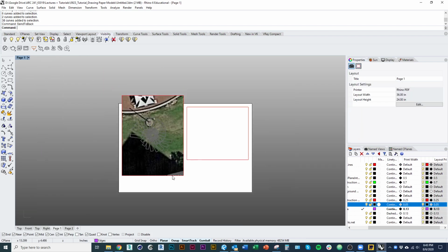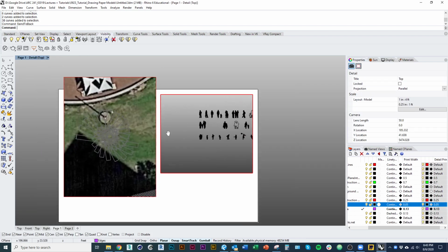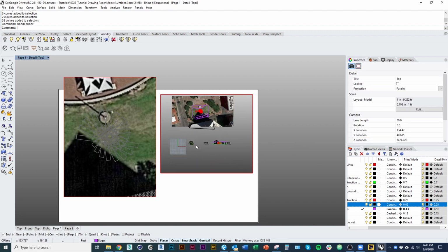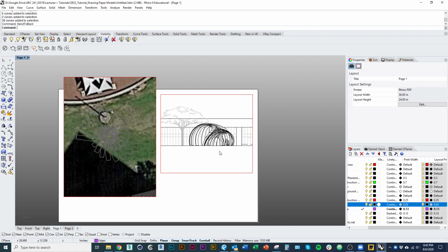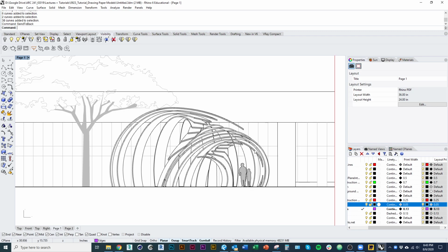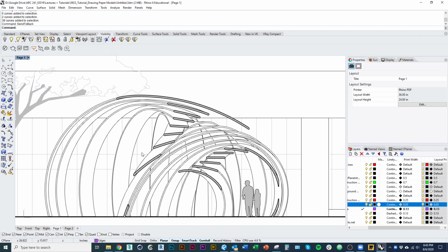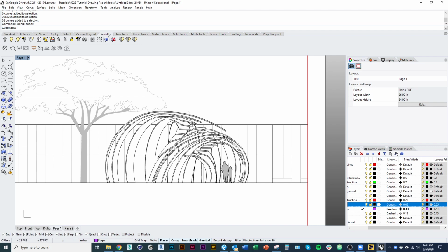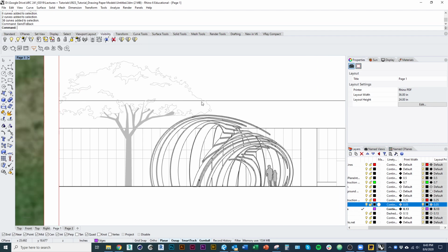And when I go look, so what that will do is it'll make it look like we're blocking out the background wherever we're not looking through it towards the building. And I would do the same thing for my tree there as well. I would block it out, or actually, you could block it out or you could trim it. I think in the case of this example, it'd be easier to hatch.